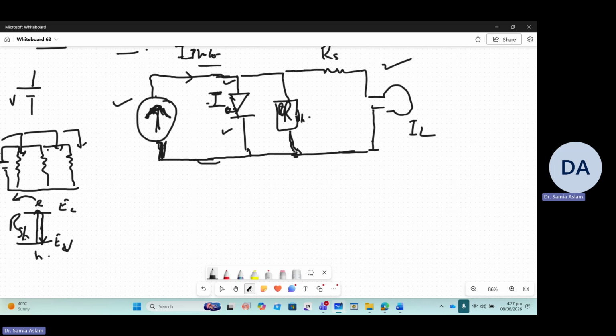This is the kind of resistance which should be very high. And you know that according to Ohm's law, when the resistance is very high, the current is very low. So this resistance has to be very high, because however, this resistance is definitely representing a path which is drawing a current. It means some of the recombination is taking place. However, this is the resistance which occurs due to grain boundaries, structural defects, interface defects and contacts, all that depends. This is known as series resistance.